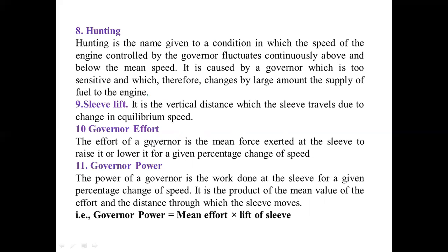Governor effort. What is effort? Effort is nothing but a force. Governor effort is the mean force exerted at the sleeve to raise or lower it for a given percentage change of speed. Whenever the speed increases or decreases, a certain speed change happens. For that speed change, there will be some mean force exerted at the sleeve to raise or lower it. That is called governor effort.